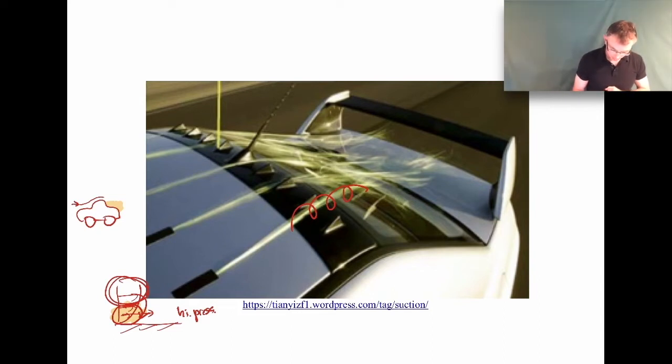Normally the boundary layer would separate and you'd just get flow going this way. And so you'd have a large low pressure region, I should say this is not high pressure, but the pressure is increasing in that region. So what ends up happening is the boundary layer can't make its way into that increasing pressure region. We call this an adverse pressure gradient, and the flow separates.